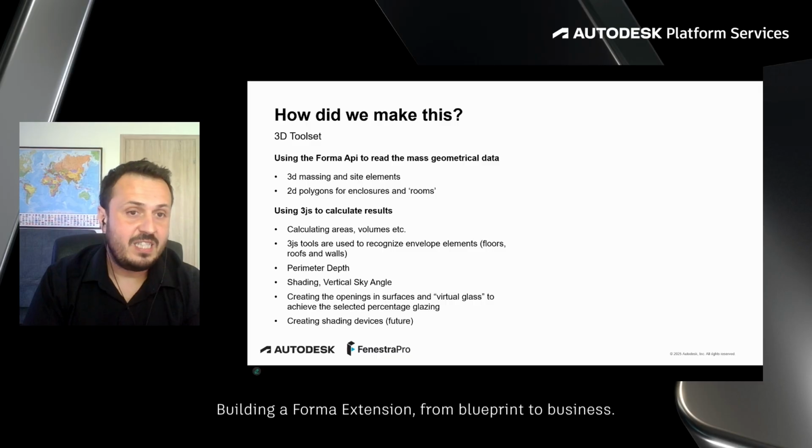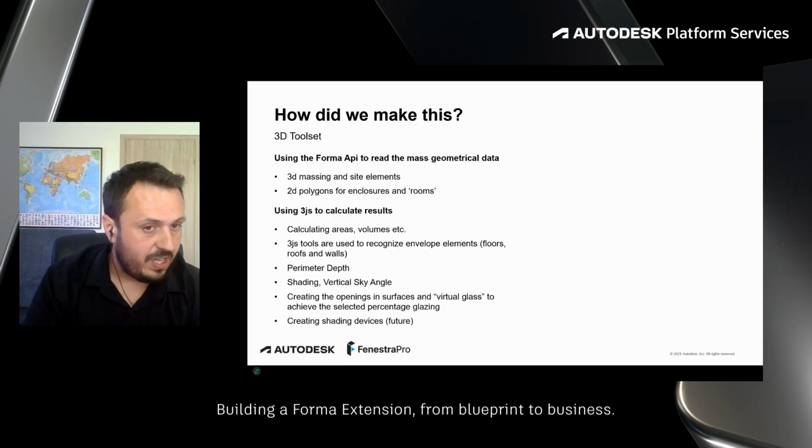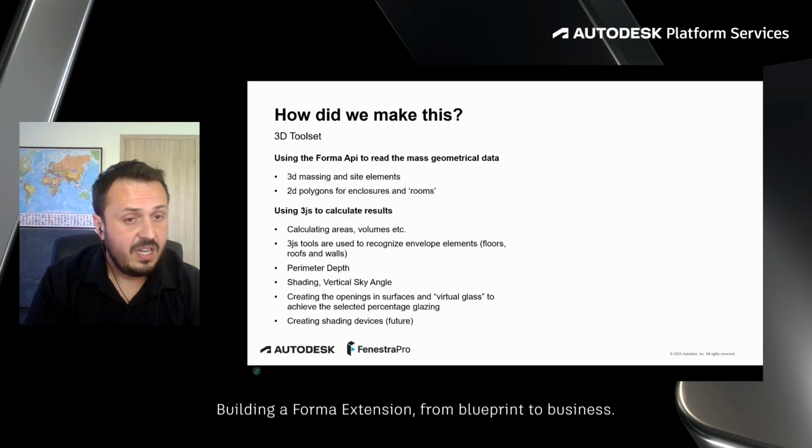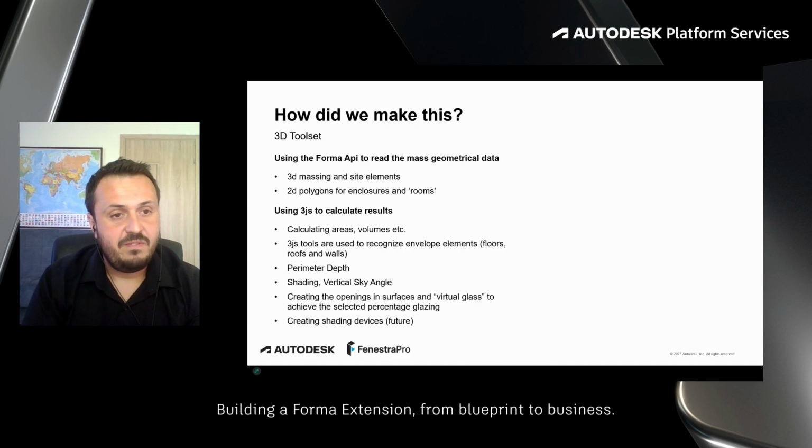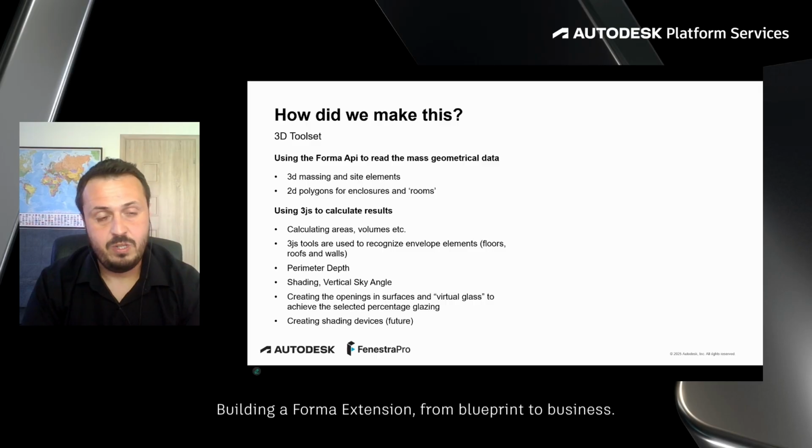We don't analyze the surfaces of the interior walls that are going inside the building. We only analyze these 2 faces that are directly exposed to the exterior light. In that nice-shaped space, we will have 2 analytical surfaces, where one face will be one surface.